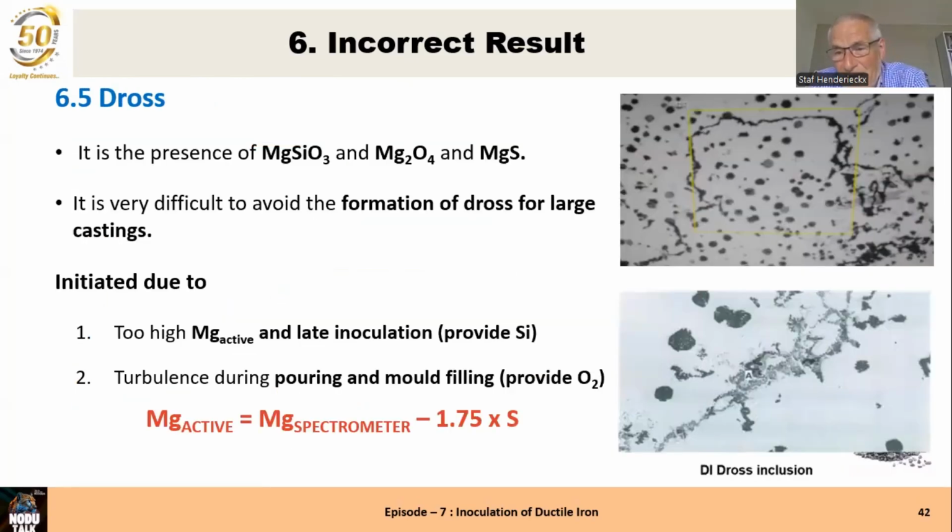You see at the right side, dross, it's a little bit, how must I say, a slinger of inclusions that hang on one another. The nodules are concerning nodularity still okay. Nodule count is many times also okay, but not always. And what is it? It's made by the magnesium silicon oxides MgSiO3 or the magnesium 2 silicon oxide, Mg2SiO4. There is a mistake in the text there. It's Mg2SiO4 it must be.